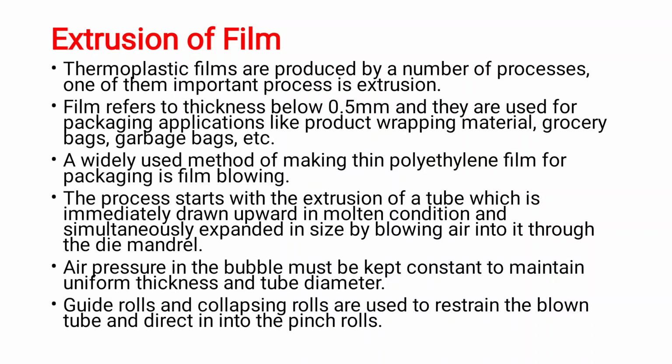The process starts with the extrusion of a tube, which is immediately drawn upward in molten condition and simultaneously expanded in size by blowing air through the die mandrel.